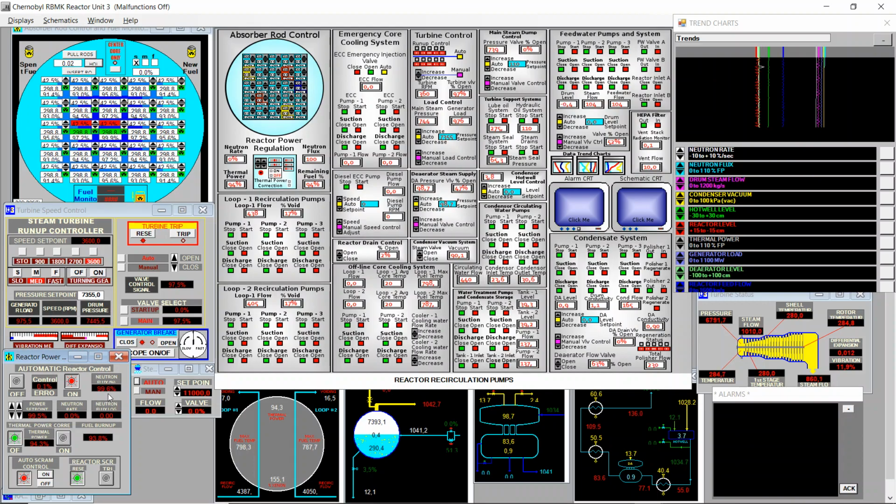We need to be really careful at this point because any change in void, like turning on suddenly two pumps in the loop 1 and loop 2, could create a meltdown by a sudden increase of neutron flux, or any other sudden change in the systems could create a meltdown now. We have a generated load of 980 something, and this is oscillating because we are in auto control, so the main valve is opening and closing between 97.7 and 97.3 to keep this pressure set point.